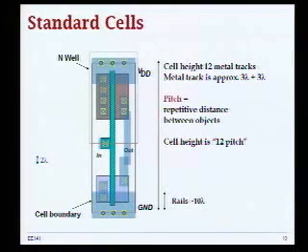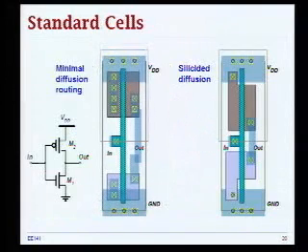So that's the strategy, to try to make this cell in a way that is really useful for high density integration. And additionally, you may want to put your input and output pins over here at a certain height, such that when you route the two cells next to each other, all you need to do is basically just put a simple horizontal line, and that will ease your routing job. Okay.